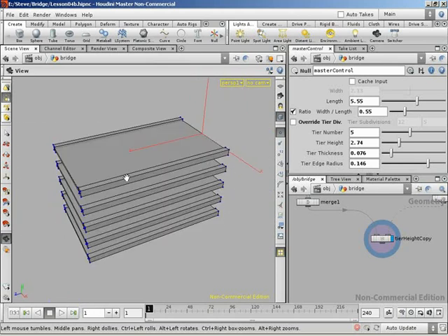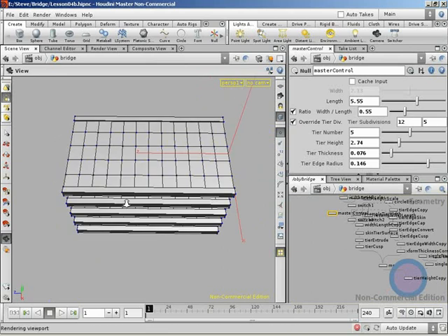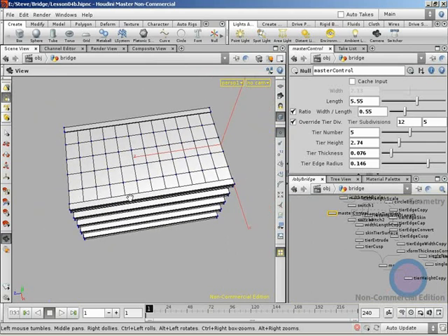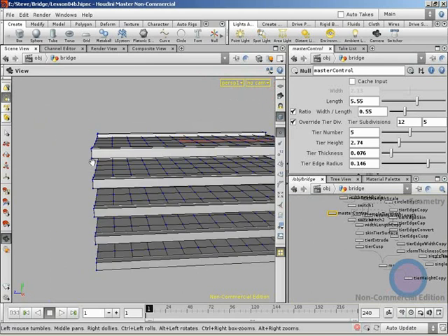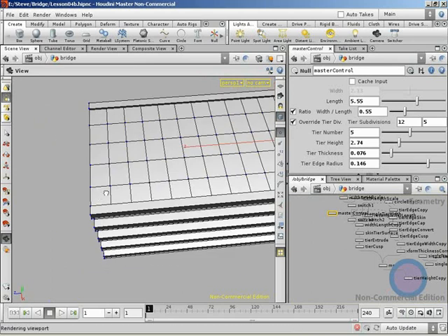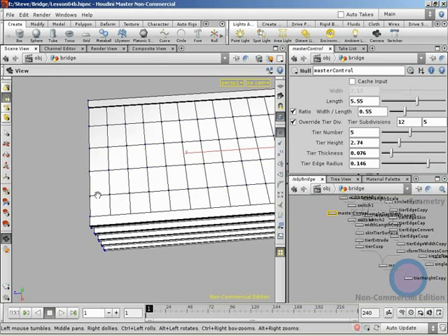We have, if I also grab our master control and override tier divisions, we've got these divisions running along in length, and what I really would like is basically a diagonal line that runs in length for one of these divisions, and runs in height from basically in between the two tiers, so that we have a diagonal line that's running across from one tier down to the other, that's length is controlled by this division set up here, so that when we change the number of divisions, we'll get a different number of those crisscross patterns.